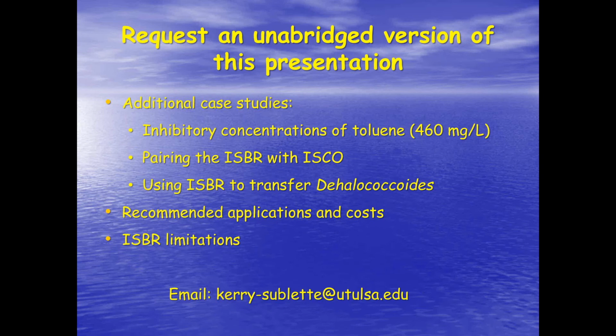So the radius of influence is going to depend a lot on the aquifer matrix, but it's also going to depend upon the growth characteristics of the degraders in that particular aquifer matrix. And if they can make it 10 meters in 3 months through a silty aquifer, then I think we're going to have a significantly high probability of large radii of influence in most of these aquifers.